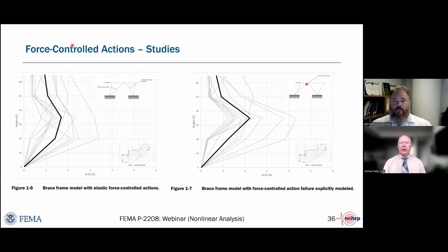In the same force-controlled actions, you talked about overstressing a member. Are you referring to demands going beyond the yield strength of the member at any time, or is member strength considered as yield capacity times some overstrength and ductility factor? What we're talking about is having some way to check what the force would be at the connection in each of your 11 records, and comparing that.